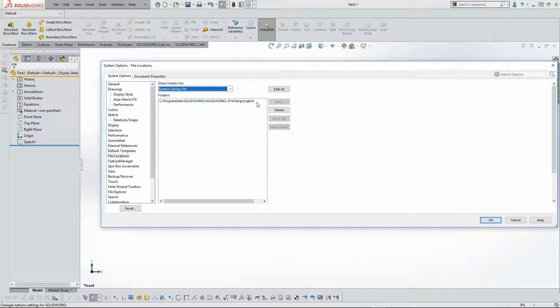And this happens more often than not where you are installing SOLIDWORKS on top of an older version of SOLIDWORKS, and when that happens, SOLIDWORKS is supposed to remove all the old data. And actually, you as the operator should go in and uninstall the old version of SOLIDWORKS and wipe out everything on it, the DLLs, everything, and it's called a clean uninstall.